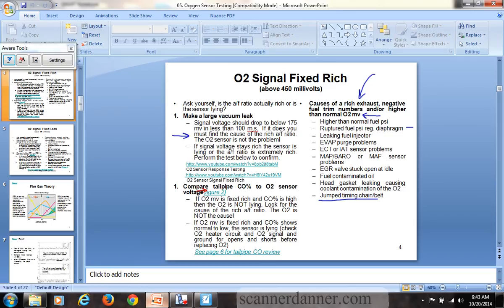Can I, instead of making a vacuum leak, flutter the gas pedal? And by flutter the gas pedal, I'm saying rapidly pump the throttle. So maybe add that in here. Instead of this, this should be 2, I guess, huh? 1 and 1. That should be number 2. Is yours like that too? Yeah, that's a misprint. 3 would be, let's add a third one. 3 would be a rapid throttle test. Would you know what that means down the road? Rapid snapping of the throttle, maybe add that word in there.